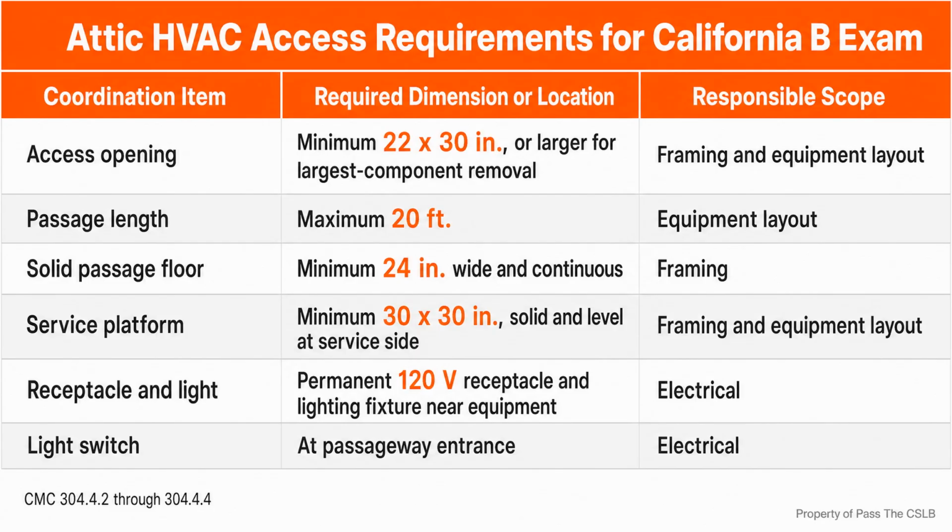If there is a secondary pan, I confirm it sits beneath the equipment, has a separate drain at least 3/4 of an inch in diameter, and terminates where occupants can readily observe discharge. If there is a shutoff device, I make sure testing and responsibility are assigned. Finally, I walk the service path.